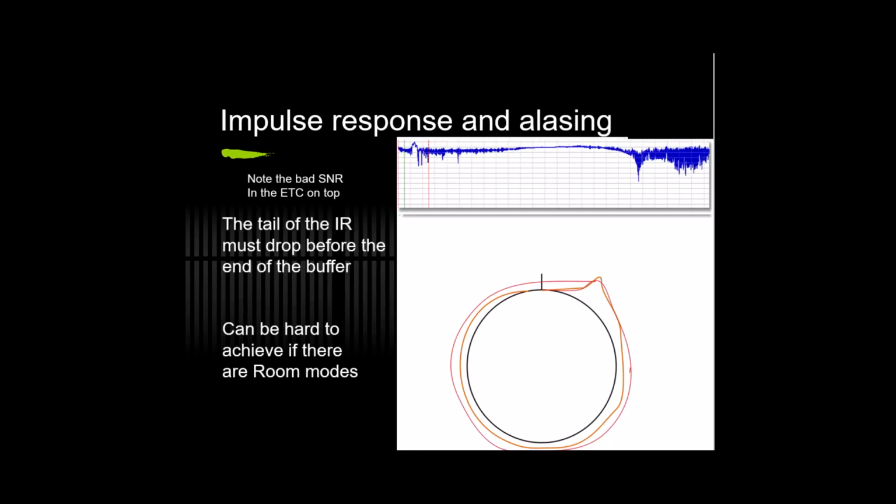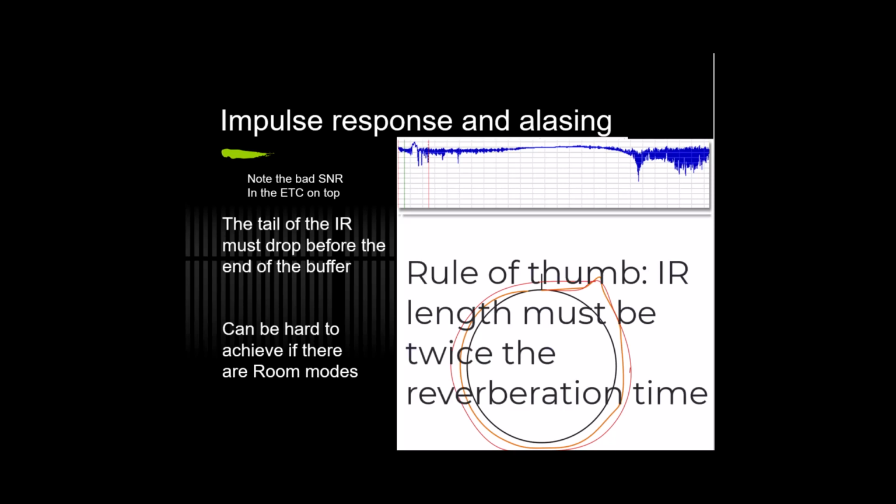I have seen this problem in many files which have been sent to me from users. And their problem has been that they have aligned their top systems to the room resonances instead of to the subs. To measure room resonances, they require a quite long impulse response, at least 4 seconds and so on.